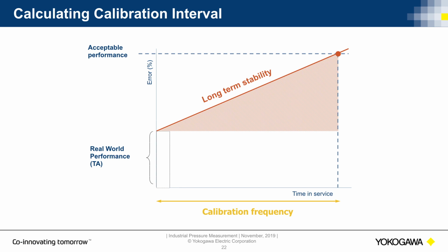So again, that overpressure effect is really critical. A common application is drum level in a power plant, where you might have really high static pressures, maybe 1,000 psi on each side of a DP transmitter, but you're trying to measure a really low differential, let's say 20 inches of water.